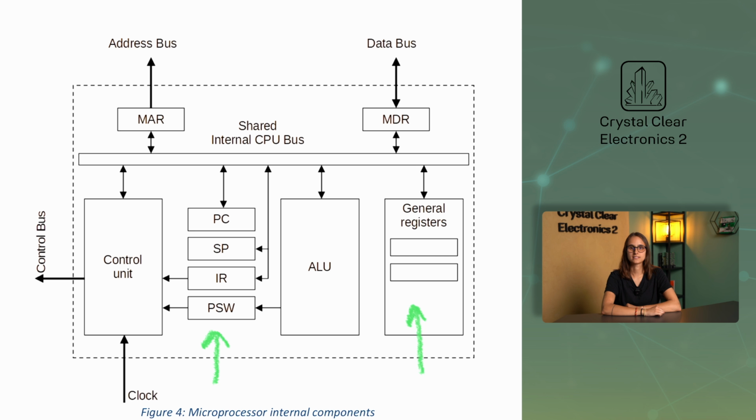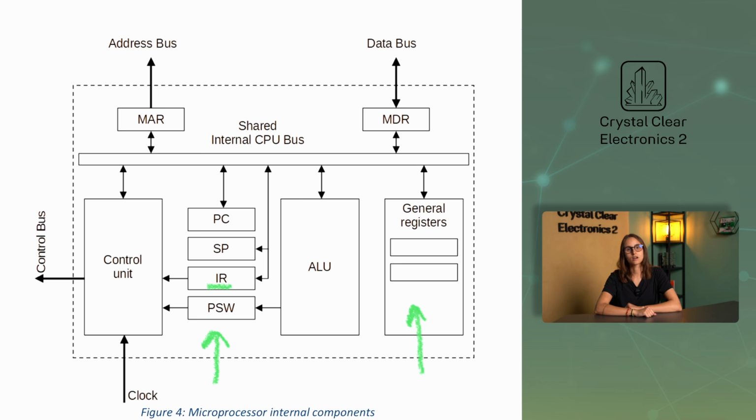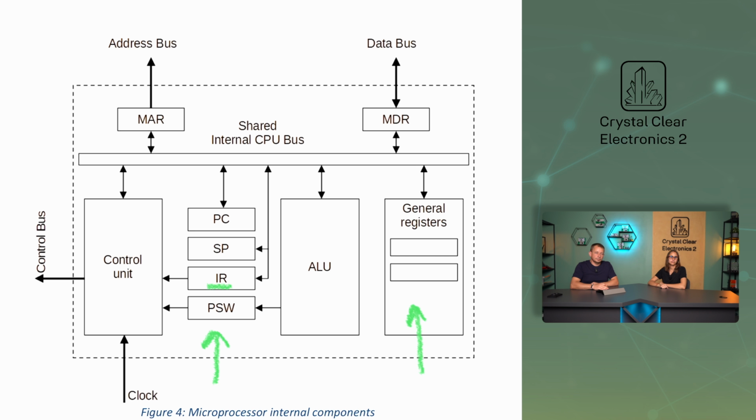The instruction register, or IR, contains the instruction, its binary code, that is currently being decoded and executed. An instruction is information stored in binary format that tells the processor what data to process and what operation to perform. Instructions are always specific to a particular processor and are executed in several steps: fetch, decode, read operands, execute the instructions, and store the result. Depending on their type, they can be data and memory management, arithmetic logic unit or ALU control, program flow control, or processing unit state control instructions.